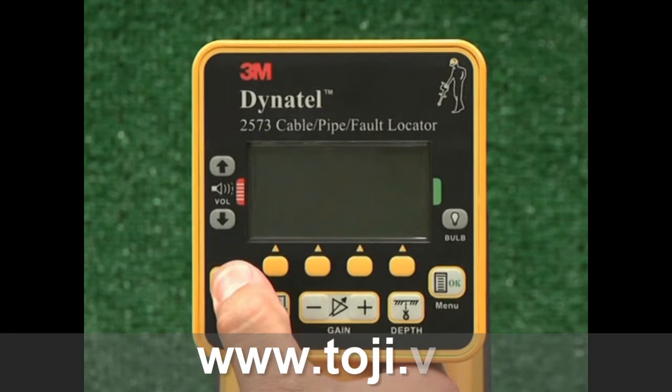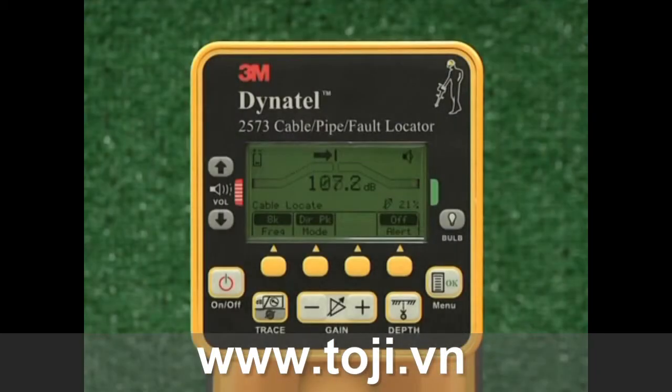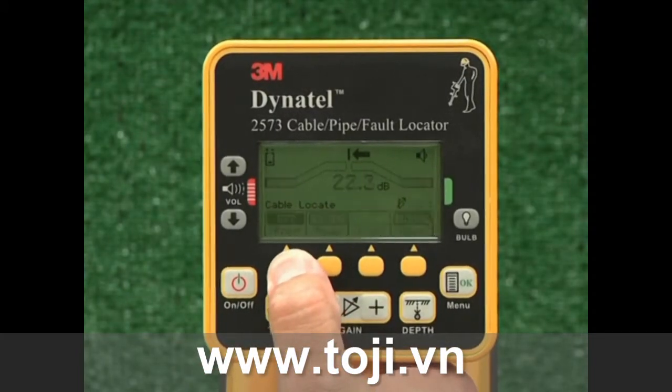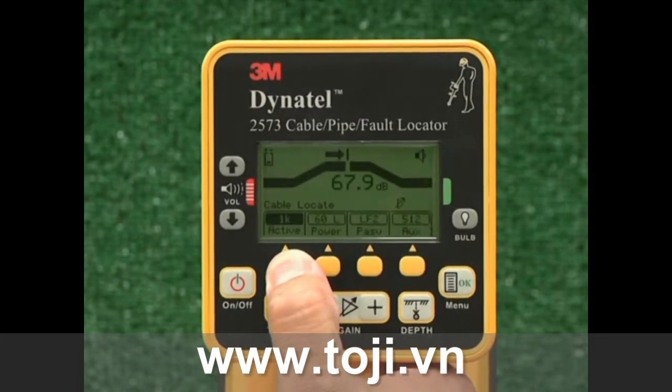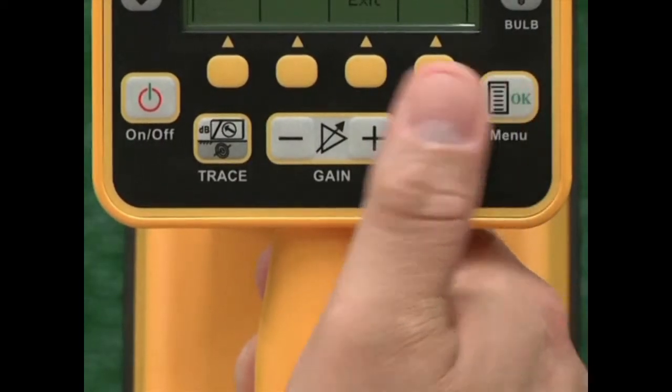Turn the receiver on by pressing the power key. From the main locate screen, select Cable Pipe. The locate screen will appear on the receiver. Press the first yellow command key labeled Frequency repeatedly until the transmitter frequency is displayed above this key. Press the OK key to return to the locating screen.